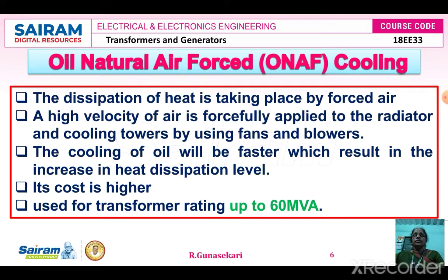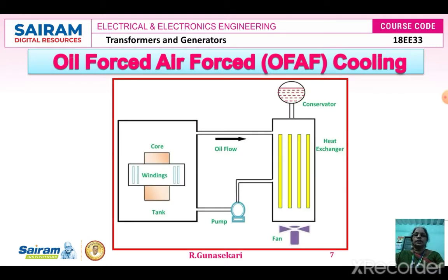So the result is that heat dissipation from the transformer is very fast. This is the oil natural and air forced type of cooling method used in the immersed type.